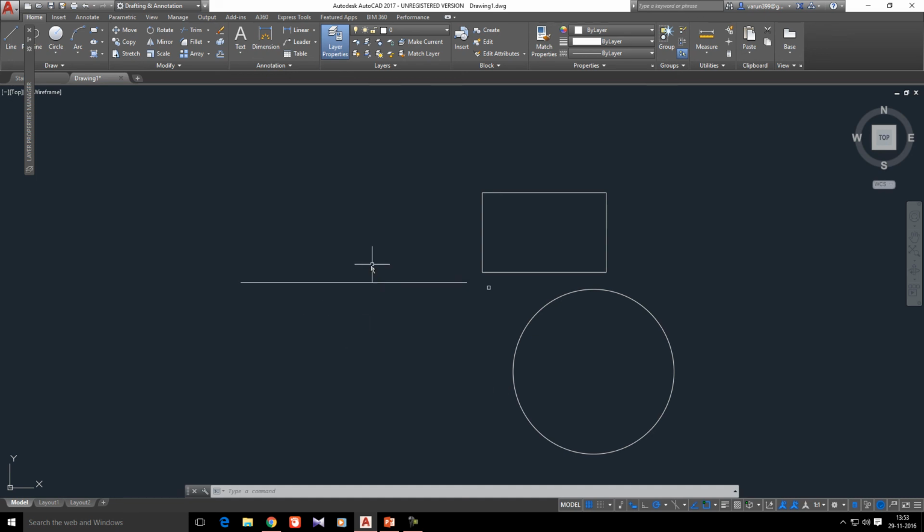Consider I have a line like this here, and let me draw another line overlapping this line somewhere like this and coming down. Let me draw another line which overlaps here and come till here. I will also draw a rectangle which starts from this endpoint and come till here, something like this. So that means there are lines and rectangles overlapping in the same place. So selecting this one will be difficult at times. So cyclic selection will help you to easily select among different objects.